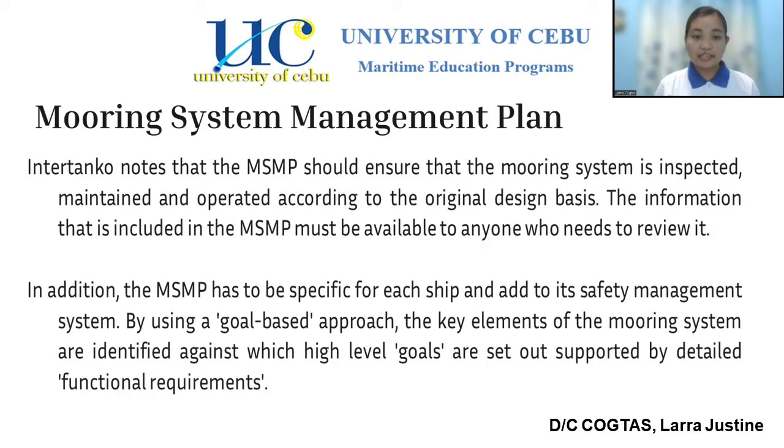Now let's add another information to the topic. The International Association of Independent Tanker Owners, also known as Intertanko, notes that the MSMP should ensure that the mooring system is inspected, maintained, and operated according to the original design basis. The information that is included in the MSMP must be available to anyone who needs to review it.